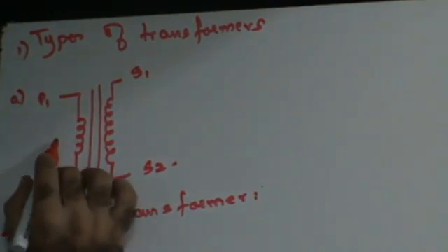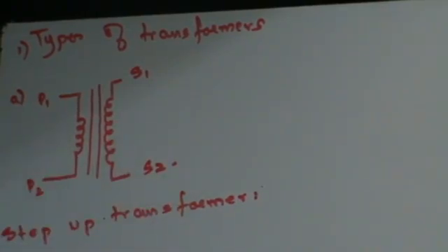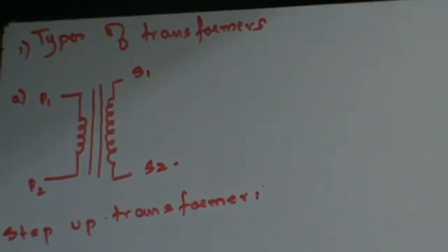The resistance of the primary is less, the resistance of the secondary is going to be more. The primary is either wound on the secondary or it is wound on two separate limbs of the soft iron core. Now, since the number of turns of secondary are more than the number of turns of primary, therefore it converts a low voltage high current into high voltage low current.